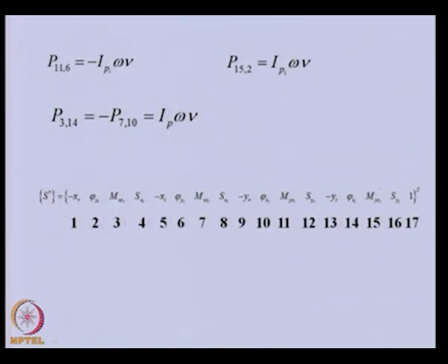That means each displacement will be represented as imaginary and real. Similarly for y and the other displacements, and also shear force and bending moment, every one will have 2 parts, because now we are considering 2 planes. Their phase may be different. So, to take care of that, we write them in the form of a vector of complex quantities. So, you can see this is the stacking of the state vector.